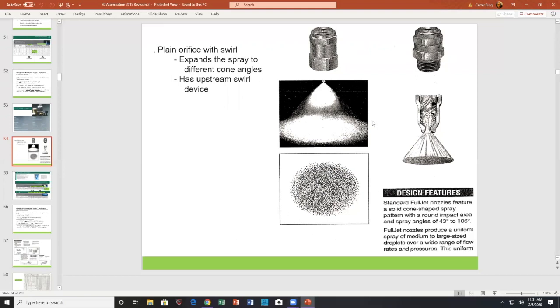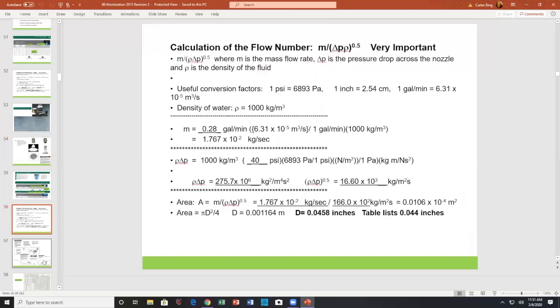I was in Amsterdam giving a course, and this one young lady had a pressure drop across a valve of 300 psi. And she wanted to know why, after 1 month's time, the valve would disappear, right? At huge pressure drops, you had huge velocities, and at huge velocities, you had significant attrition or significant abrasion occurring.